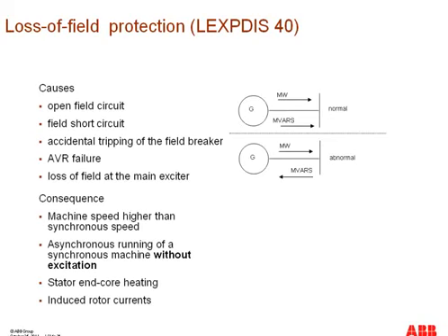So let's talk about the loss of field protection. The IEC 61850 logical node for loss of field protection would be LEXPDIS, and the ANSI number is 40.